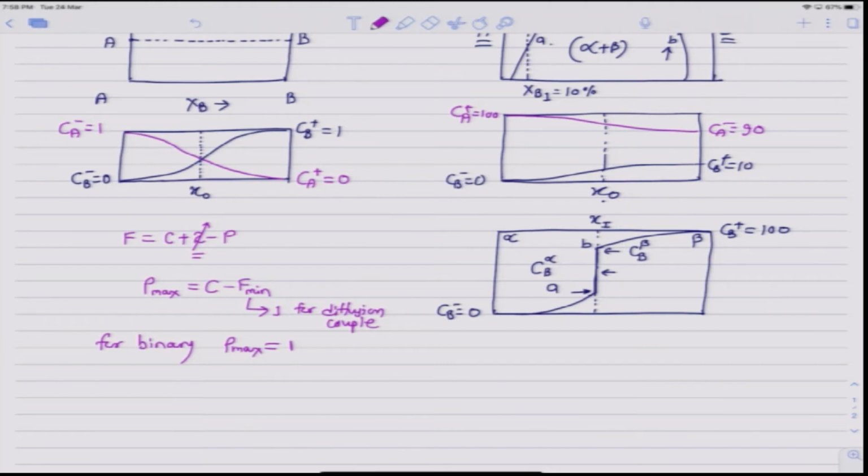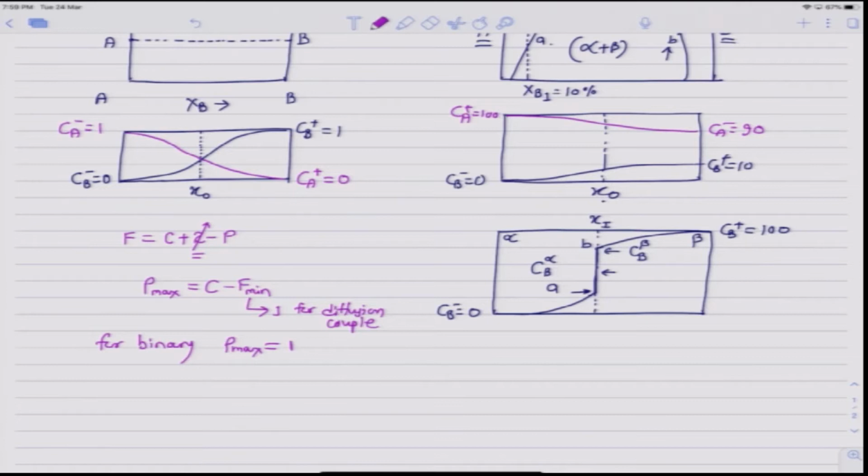There may be multiple single phase layers within the diffusion zone, but in a given layer there will exist only one phase. Two phase layers cannot form because of the constraint from the Gibbs phase rule. Also, the interface between the two different phases formed in a binary diffusion couple, which is annealed at constant temperature, has to be a planar interface.